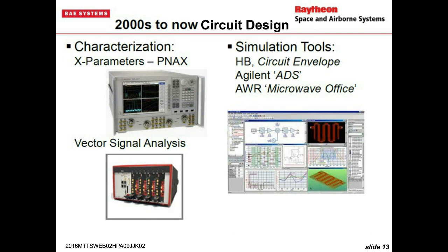And that took it another step, that you could separate the data rate, which is even slower than the modulation, from the RF carrier, and do things like error vector magnitude calculations on modern bandwidth efficient modulations that are used in modern communication systems.